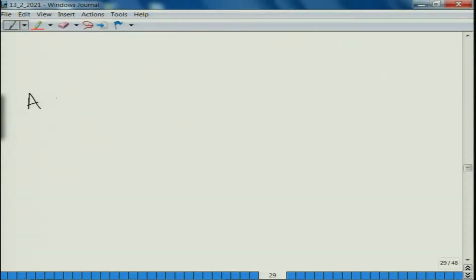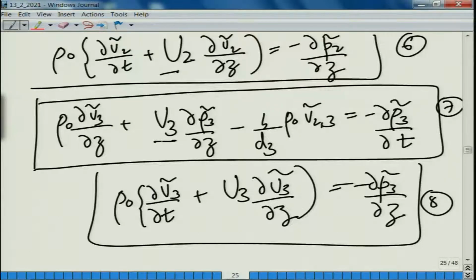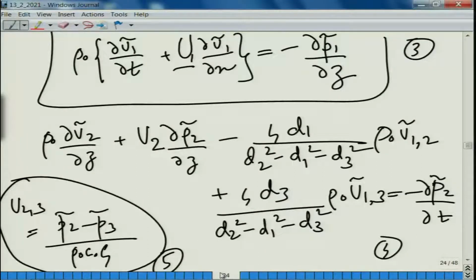So, the A matrix is then given by this, and here note one more thing that I forgot to tell: we have incorporated the convective effects of mean flow by the underlined terms. Here we have these underlined terms, u2, u3 and so on, and u1 also in this duct. But for simplicity we can ignore the convective effects of mean flow altogether in the ducted system, and just consider the dissipative effects of mean flow. And how do we do that? We incorporate the dissipative effects into the perforate impedance expression.